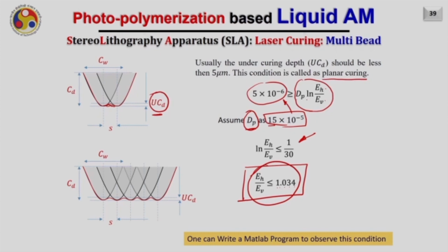So, for example, if this is my first pass, this is my second pass, this is the third pass, and so on, where the energy is maximum, you can easily observe here. The energy is maximum at this location, right? Because here you can see 3 different beams are overlapped, where the energy is greater than the EC, and hence the maximum energy will be in this region. And of course, the minimum energy will be in this region where only 2 beams are overlapping, right?